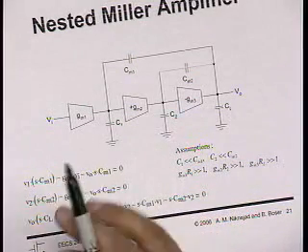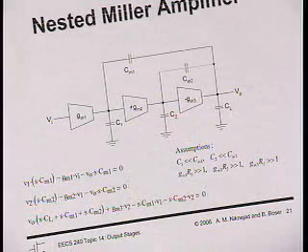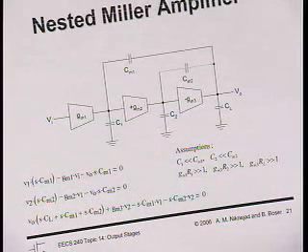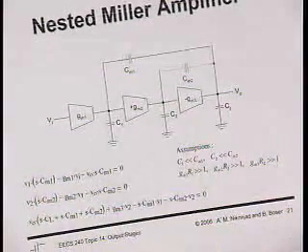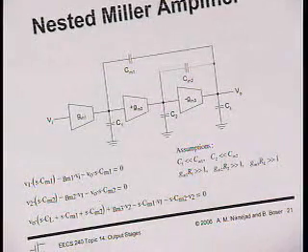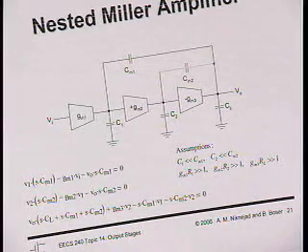But if I keep in mind that that pole at 0 is actually my dominant pole, which is not quite at 0, I can work backwards and make this work. Okay, so to analyze this circuit, there's the 3 nodes. Write down 3 equations. Make a few simplifying assumptions.